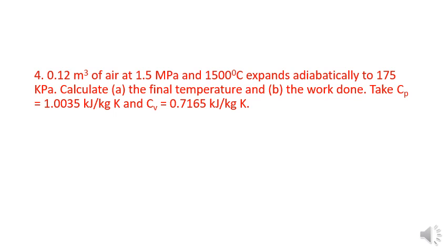So moving to the next problem. 0.12 meter cube of air at 1.5 megapascals and 1500 degrees centigrade expands adiabatically to 175 kilopascals. Calculate the final temperature and the work done. Cp value and Cv value are given.